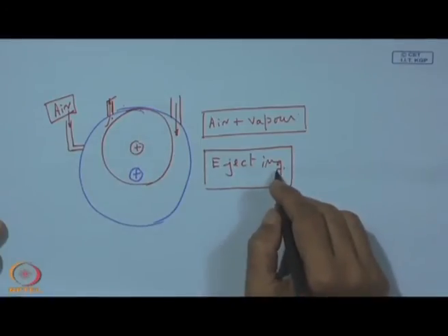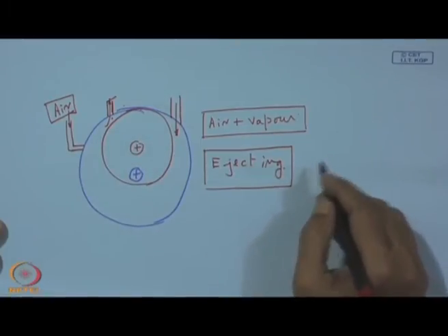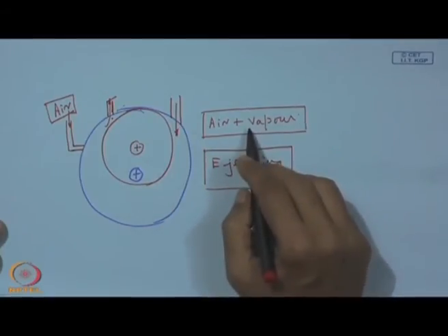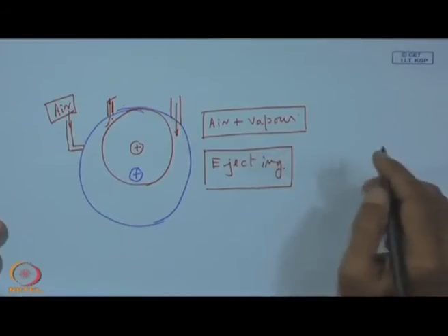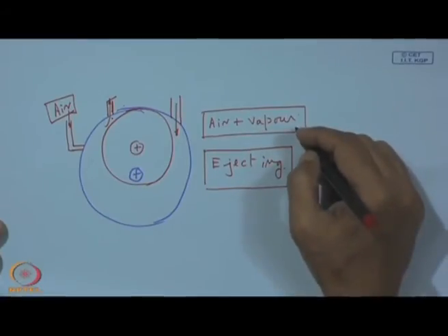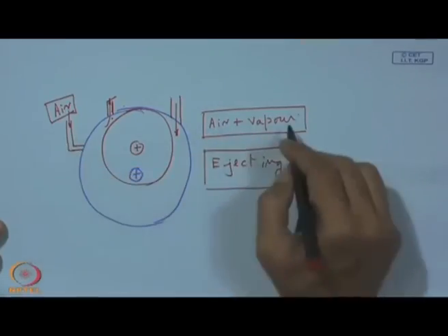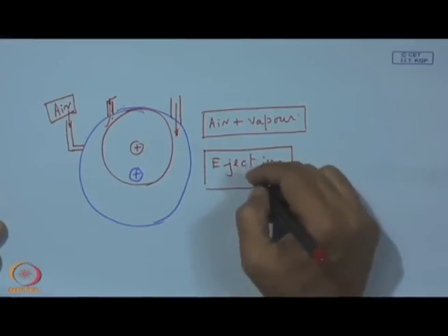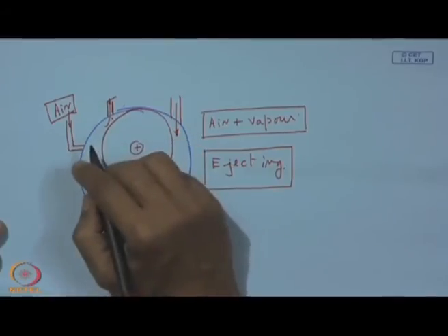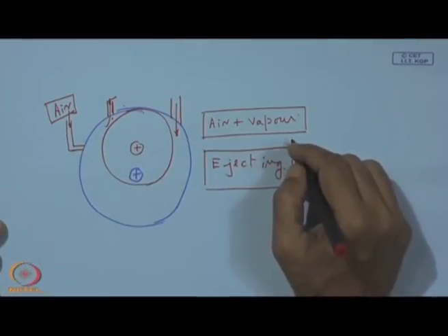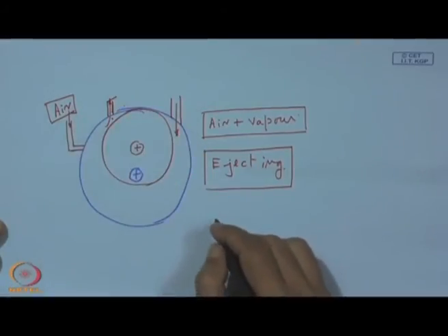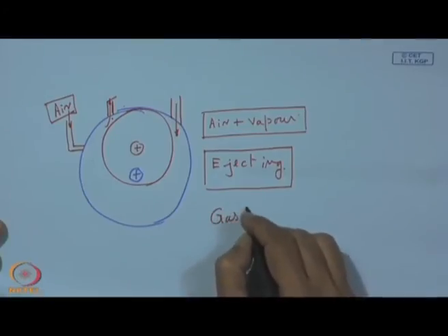So, what we do in this case, we can raise the vapor pressure for condensation of this mixture. If it had been only the water vapor, then condensation would have been earlier. So, by putting this mixture of air and the vapor, we elevate this vapor pressure. So, ejection of this mixture can be done without having any condensation of this vapor, and that is why this is air venting and that is called gas ballast.